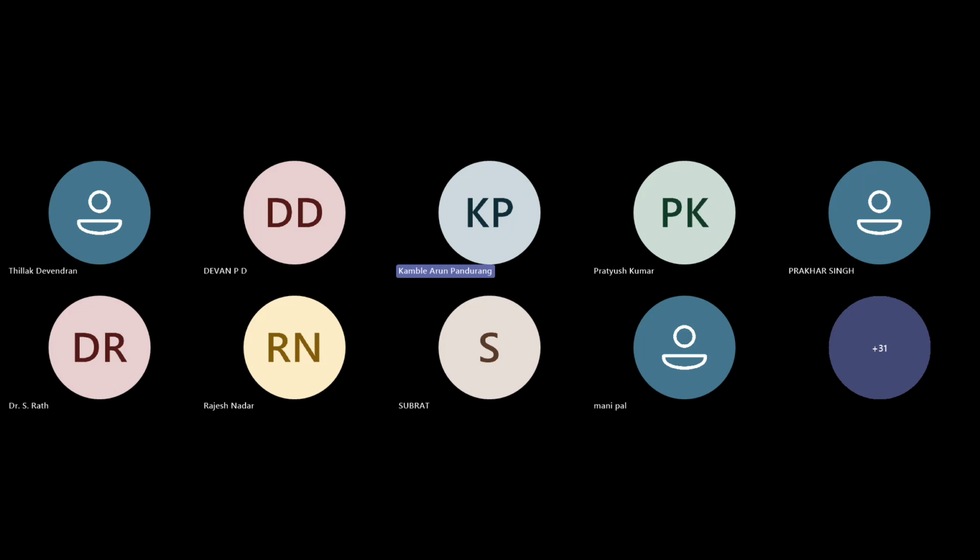And the workflow of ANSYS is very different. There are ANSYS Workbench and APDL. The workflow is different, but the main approach is the same. In both methods we use the same approach, which is finite element analysis. And LS-DYNA is generally used for impact problems or crashworthiness. Small-time problems, short-time events, we can model in LS-DYNA. That is the main difference.